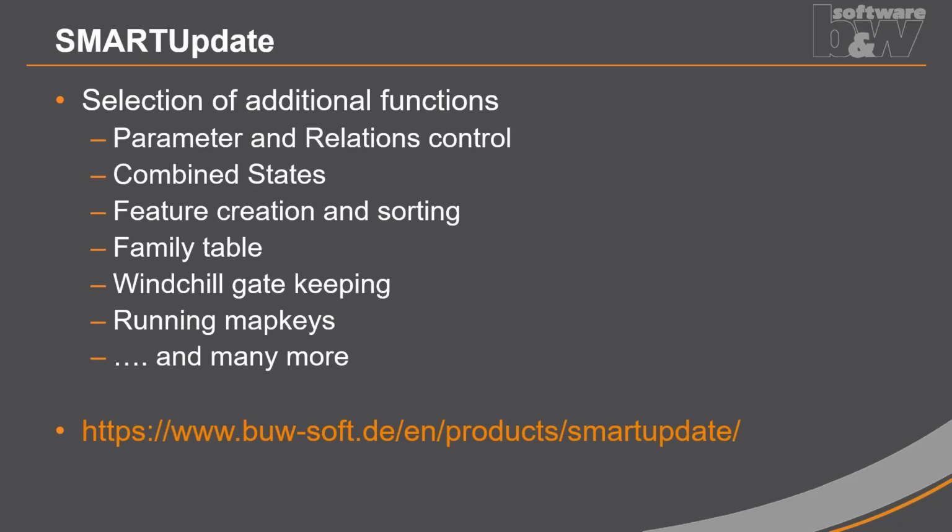And let's talk a little bit about a few additional functions of SMARTUpdate. I haven't shown the parameter and relations control where you can add and remove parameters. You can add and remove relations, and you can find relations, invalid or valid, by regular expressions, very powerful. You can create and rename combined states. You can check combined states if they're set up correctly.